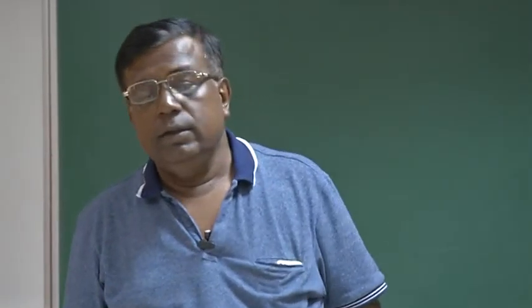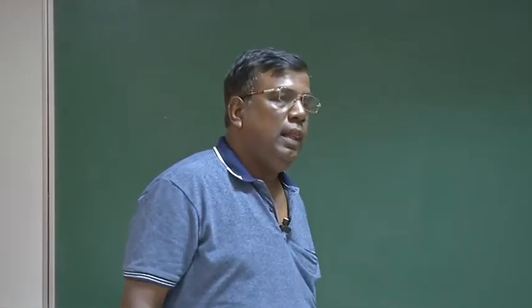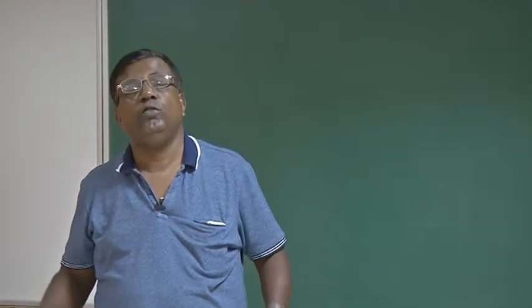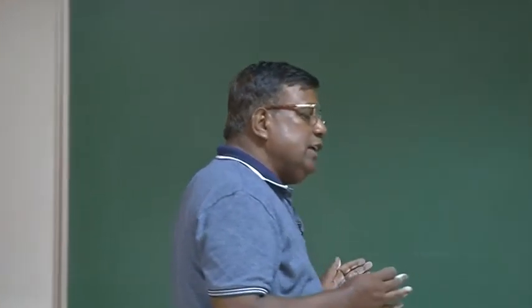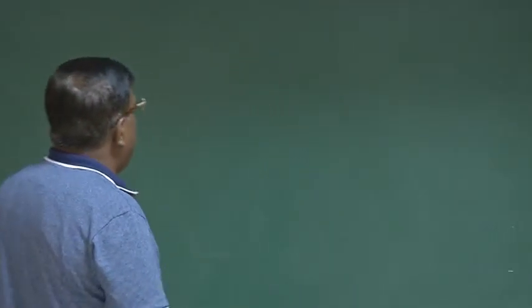When I say high speed, in today's context we mean Mach number greater than 0.3, or typically 0.7, 0.8, or supersonic, depending upon the type of airplane, you can go up to 2, 2.5. The moment you increase the speed of the airplane, you will find there is a change in the configuration of the airplane. For example, for a low speed,